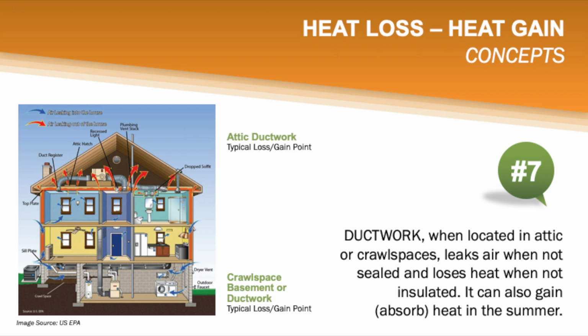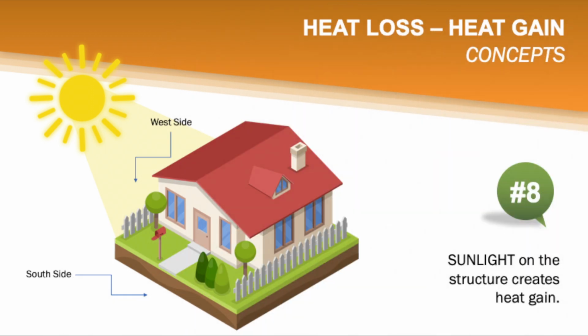Our secondary concern with ductwork is its condition. Poorly constructed or damaged ductwork can be a source of air leakage and infiltration, as well as a place for heat energy to be lost or gained. To prevent unwanted air leakage and infiltration, ductwork can be repaired and sealed, and then finally insulated. This combination of air sealing and insulation will prevent the majority of heat loss and gain, but will not entirely eliminate it.